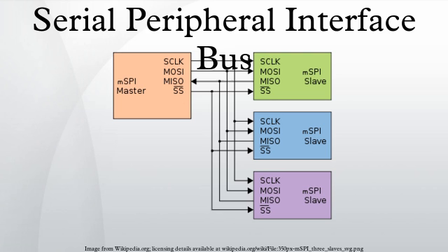Development tools: when developing or troubleshooting systems using SPI, visibility at the level of hardware signals can be important. Host adapters: there are a number of USB hardware solutions to provide computers, running Linux, Mac, or Windows, SPI master and/or slave capabilities. Many of them also provide scripting and/or programming capabilities. An SPI host adapter lets the user play the role of a master on an SPI bus directly from a PC. They are used for embedded systems, chips and peripheral testing, programming and debugging.